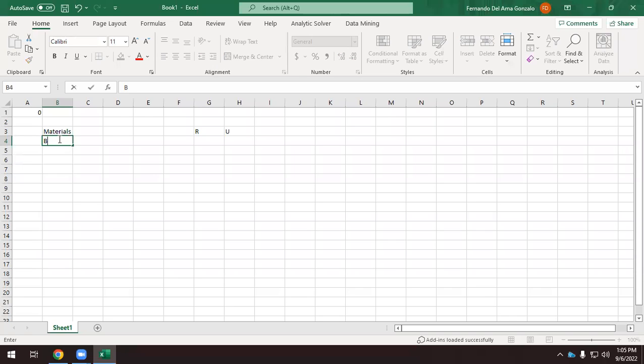Here we can have brick, thermal insulation, and plywood. Okay, so that would be the basic wall. We have brick outdoors, then we have thermal insulation in the wall, and then plywood indoors. So we have materials, and what are the parameters that we need here? So the first thing we need is the thermal conductivity.